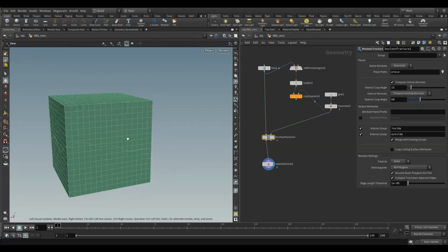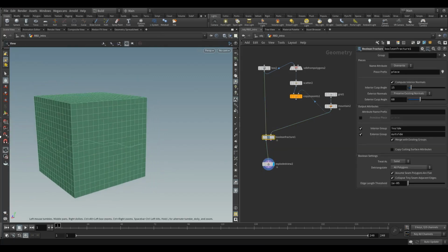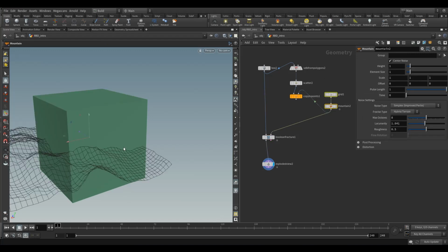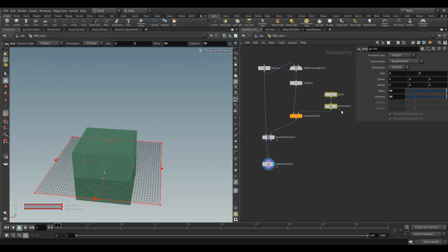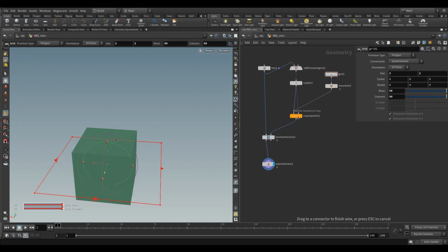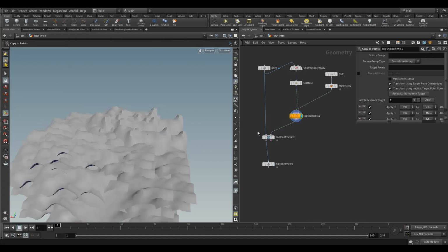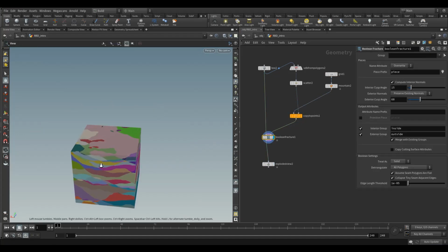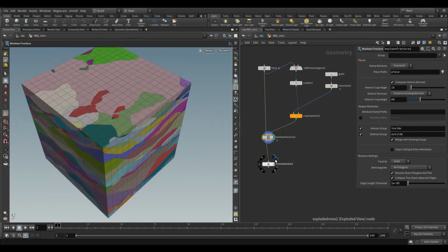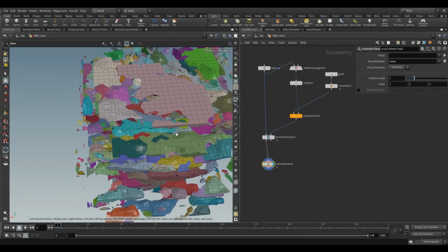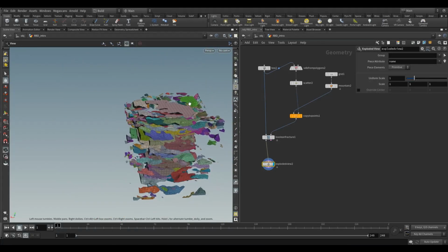You can see I've just got the one cut there with this funny kind of polyline going around it, which is no good. So we need to make sure, and in this case it's easy because we've just got the one line, but that won't always be the case. For example, if I do that, okay, so now I've got loads of pieces, and we may find this could have failed in some places, but maybe not. But it can happen when you've got lots and lots of things overlapping.